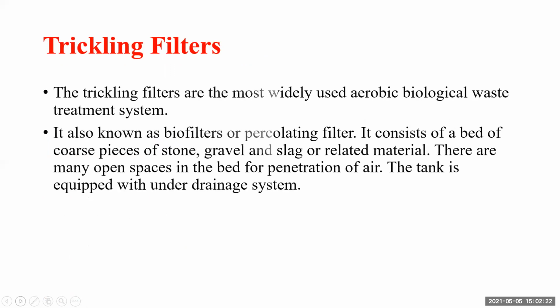So what is a trickling filter? It is a unit that is used for secondary sewage treatment, or biological treatment of sewage. Trickling filters are the most widely used aerobic biological waste treatment systems. What is it? An aerobic biological waste treatment system that is most widely used. It is also known as a biofilter or percolating filter.